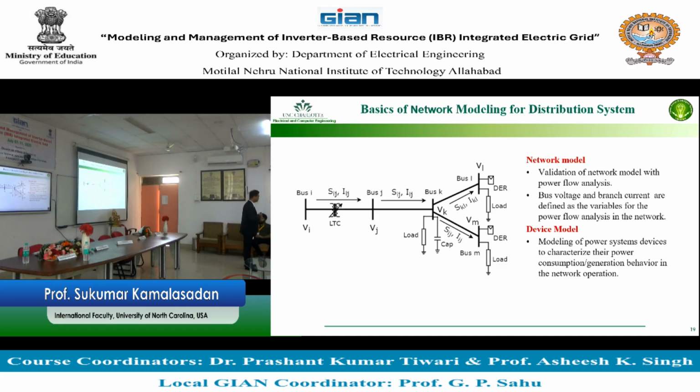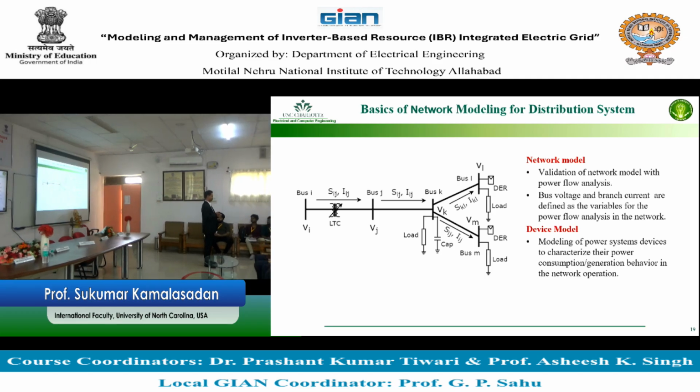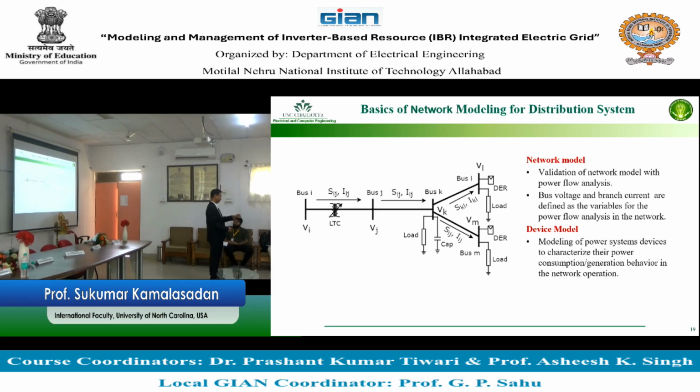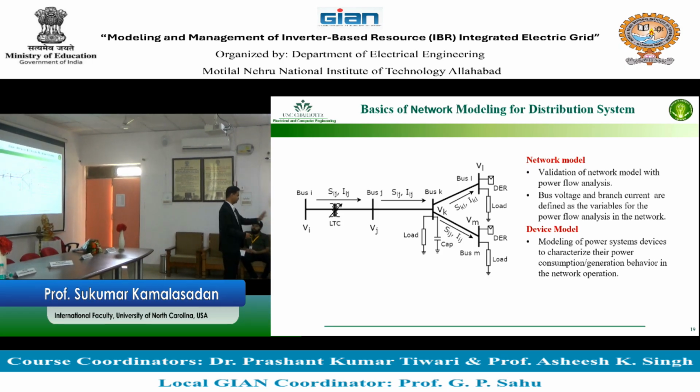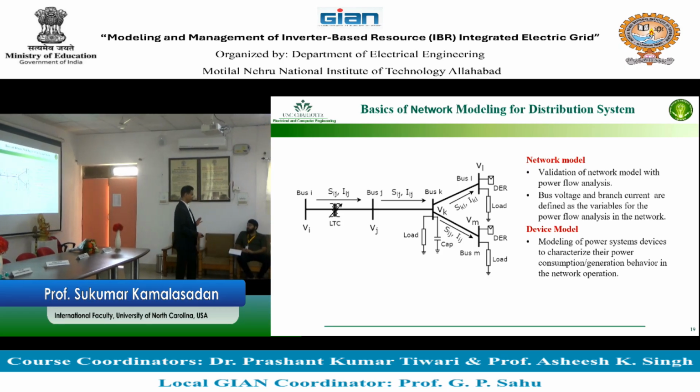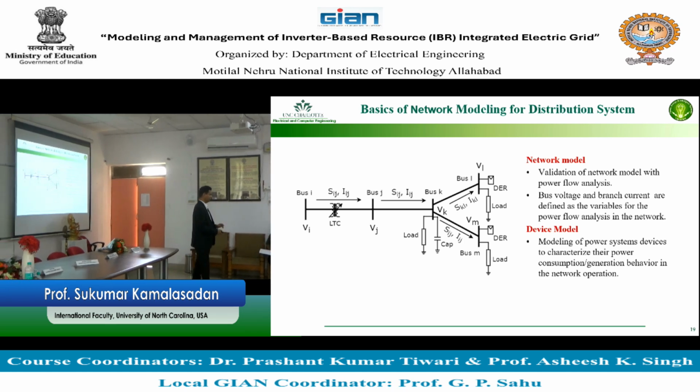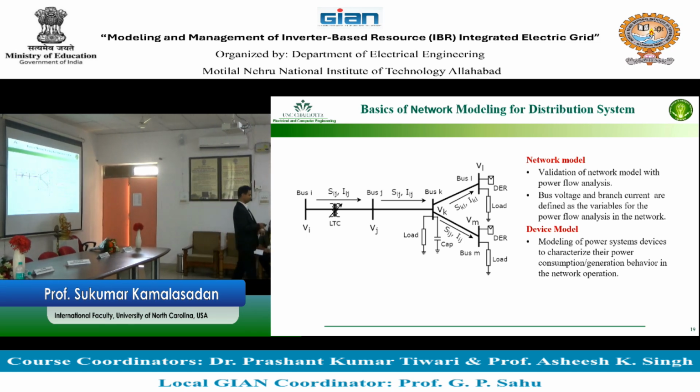One is called, maybe you may not know, one is called fixed capacitor, where you take the capacitor bank or a can and then connect to the bus, which changes the voltage directly from capacitive reactance. So capacitor is not a device changing the reactive power. Capacitor is changing directly the voltage, based on the capacitance connected to the network at that point. That type of capacitors are called fixed capacitor.